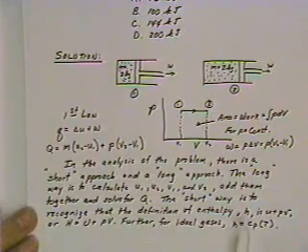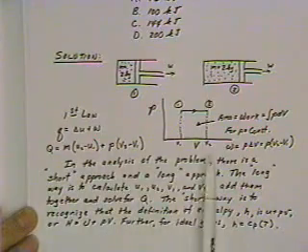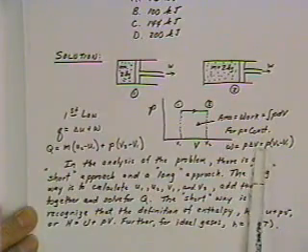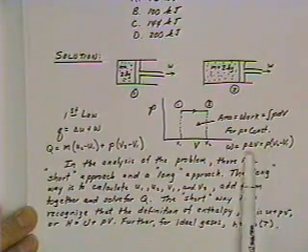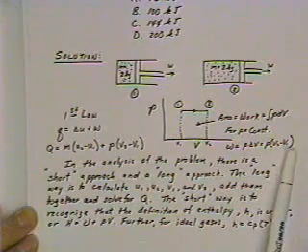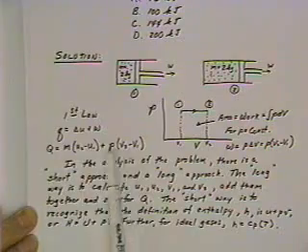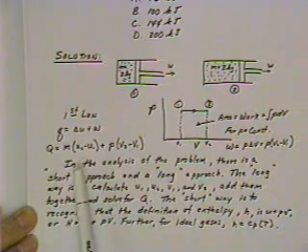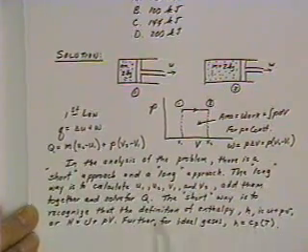And one way of looking at this particular problem is to recognize that you've got a constant pressure process here, and therefore you've got P times V2 minus P times V1. You look back at these two terms here and you notice that the definition of enthalpy, H, is U plus PV. Enthalpy H is equal to U plus PV.